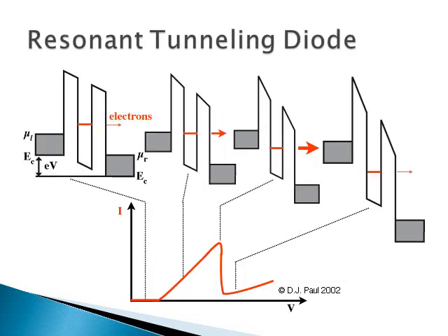A diode is any device that allows electrical current through it if voltage is applied in one direction, but doesn't allow current when applied in the opposite direction. Normally, this is achieved through a contact of differently doped semiconductors. But similar characteristics can be found by creating a potential energy profile by growing material with varying band gaps. The structure shown here and simulated later is the double barrier structure.